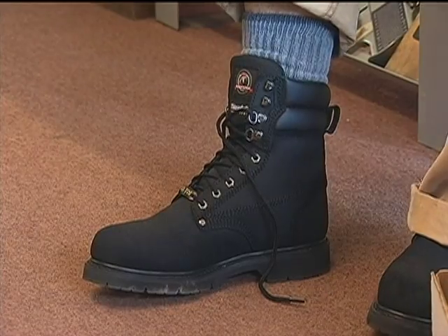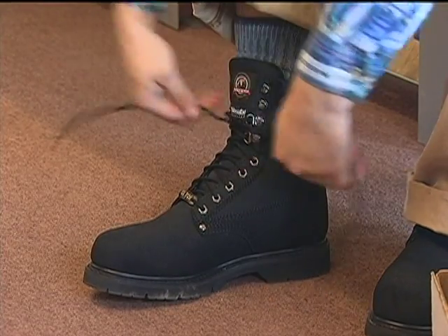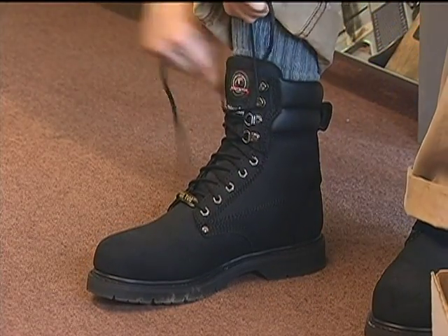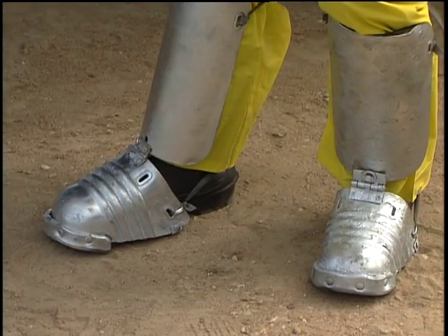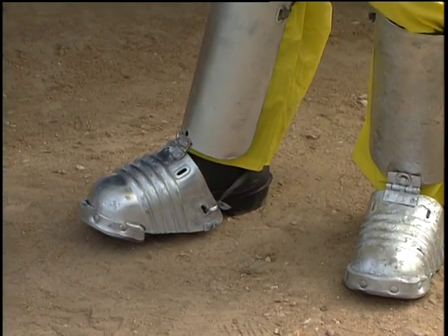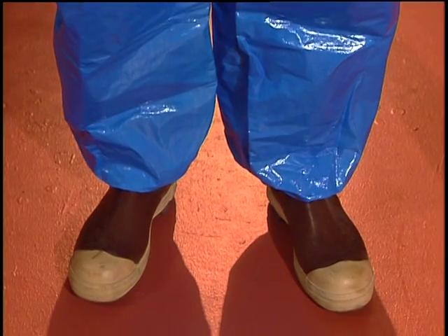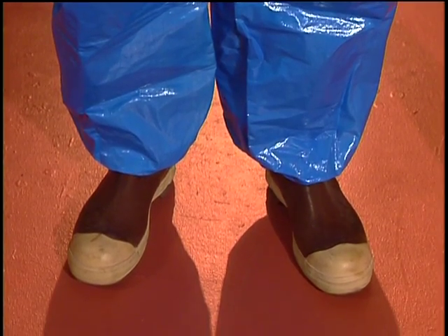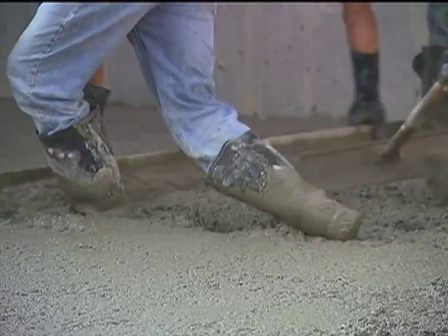Wear special types of shoes or foot guards when special hazards exist. For example, wear leggings or high leather boots for hot surfaces and/or substances, and rubber or synthetic boots with toxic chemicals. Wear rubber boots when working in concrete or in water.